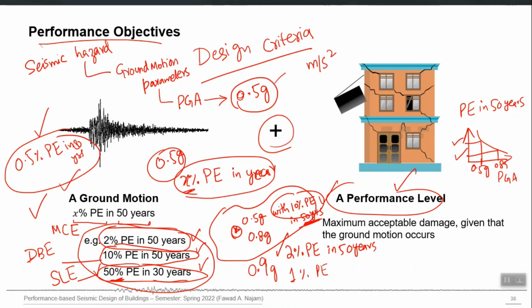It cannot be that you use an elastic model and apply a very high level earthquake, because that analysis will be completely wrong. If you are expecting damage, then the structural model should be non-linear, right. So, for design level and for service level evaluation, you can use a linear elastic model, the conventional model, but for MCE level analysis, you have to make a non-linear model and do non-linear analysis.